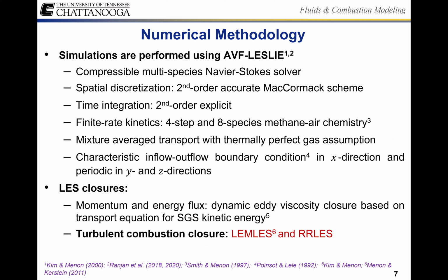For our closures, we are using a momentum and energy flux with dynamic eddy viscosity based on transport equations for the SGS kinetic energy. And of course, we are going to be using LEMLES and RRLES and then comparing the results. And actually, an added function of this paper, which we'll see at the end of the results, is that we're going to be comparing the dual grid strategy for RRLES versus the single grid. And so that adds an extra layer of complexity to this study.